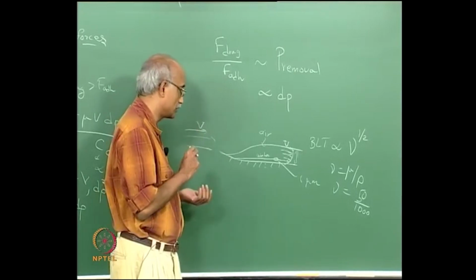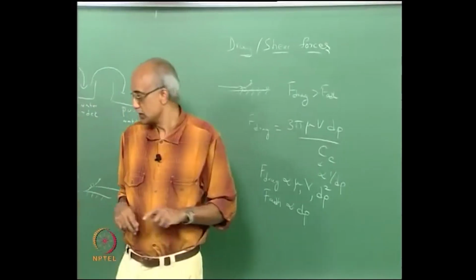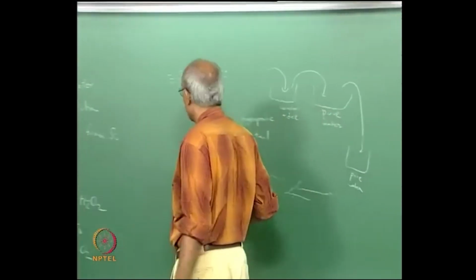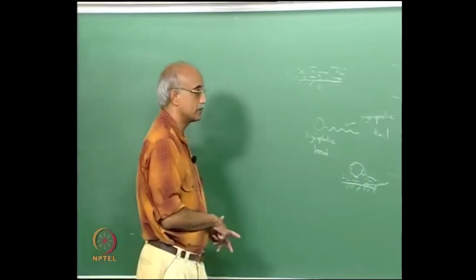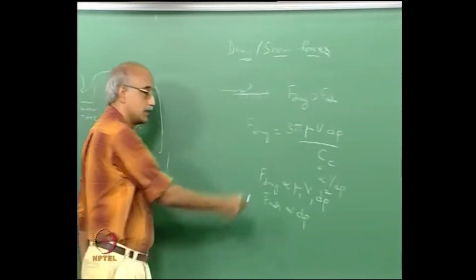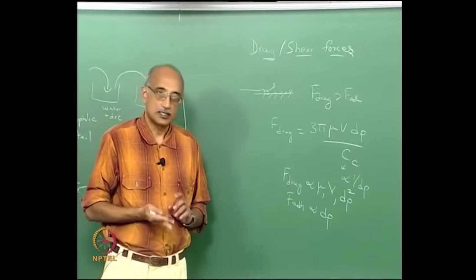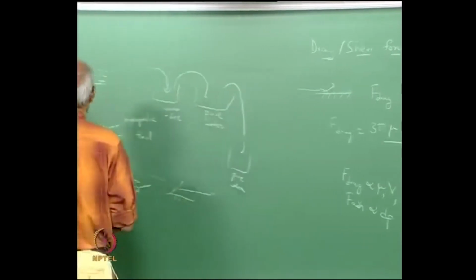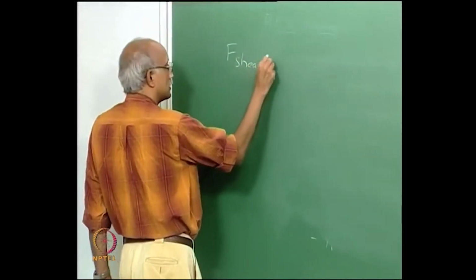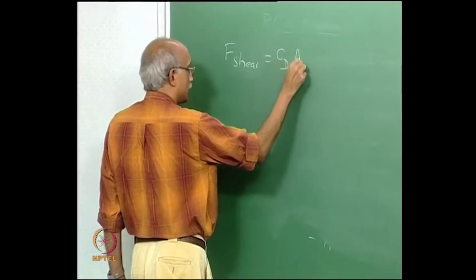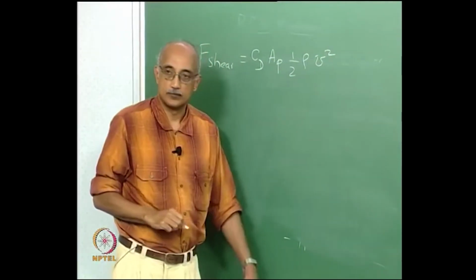Now when we talk about this type of cleaning mechanism, the drag force of course changes as you change the velocities. That expression that we have written earlier is applicable in conditions where the velocity is relatively very low. As the velocities increase, the expression for shear force becomes a drag coefficient times area of the particle times half of rho u squared, right.